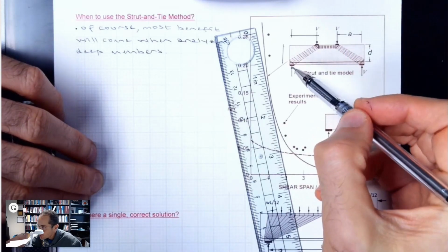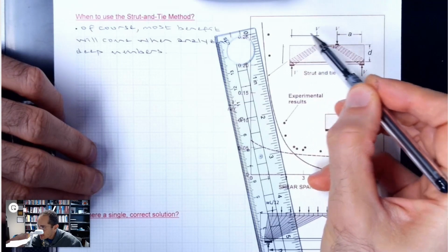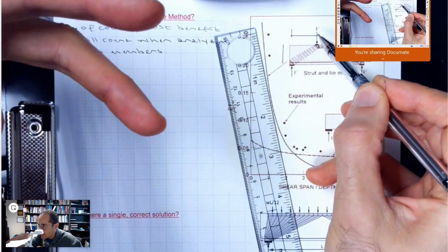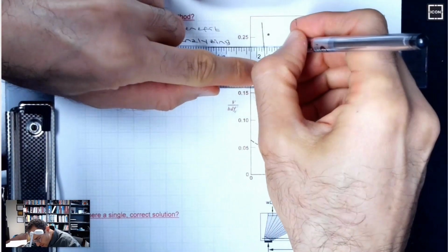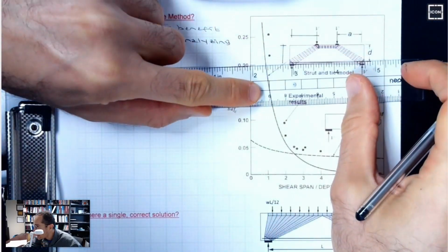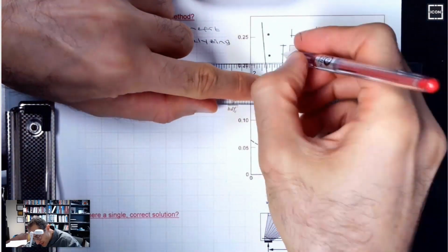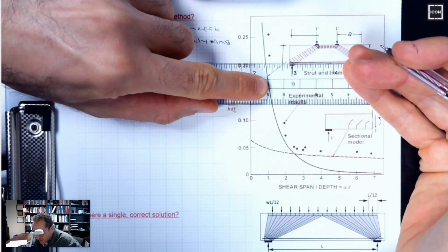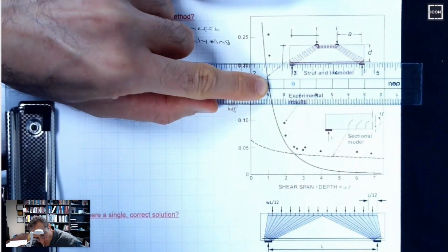So if you have that 2 situation, depth to shear span of 2 would make it a deep member. I would refine this a little bit more. I said H previously, but typically H is effective depth, because concrete behind, underneath reinforcement does not really work.